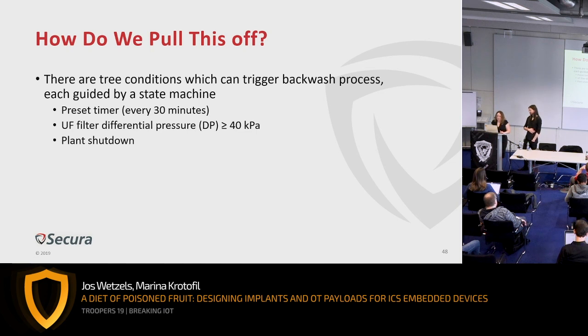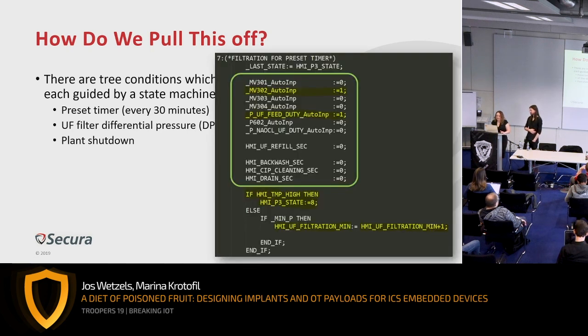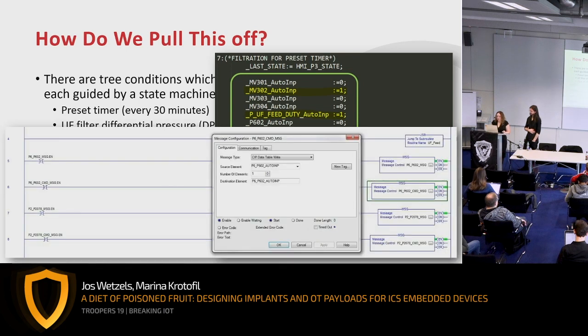The triggering of these events will be based on the state machine. The state machine knows the position of every control actuator in the plant at the current moment, and it has to follow this specific state so that you could start both processes. But most importantly, the state machine is only in the PLC in stage number 3, but not in PLC number 6. And we want to start the backwash process in PLC number 6. The process will start in PLC number 6 only by one variable, which comes from PLC number 3.